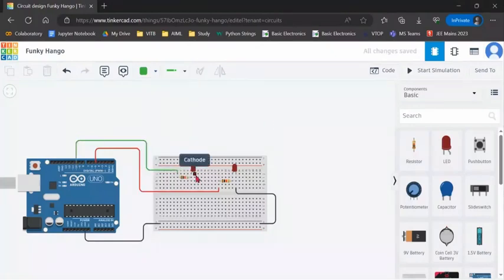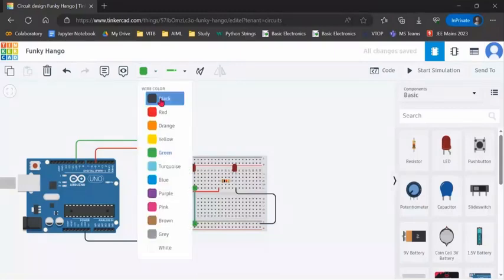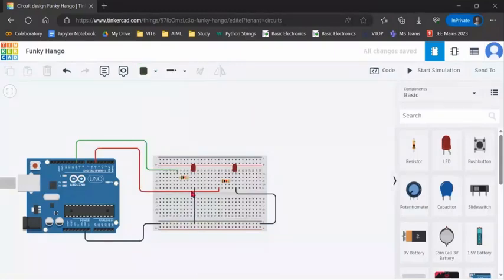This should be connected to the ground, and it should be ground, so it is black. Once we have crossed two different terminals, it is not connected, because if we highlight it, there is no highlight of this black color. If we cross two wires, there will be no connection. If you want to make a connection from here, we need to drop here, and then start and drop here, then it will be a connection. If we are crossing a wire, there is no connection.